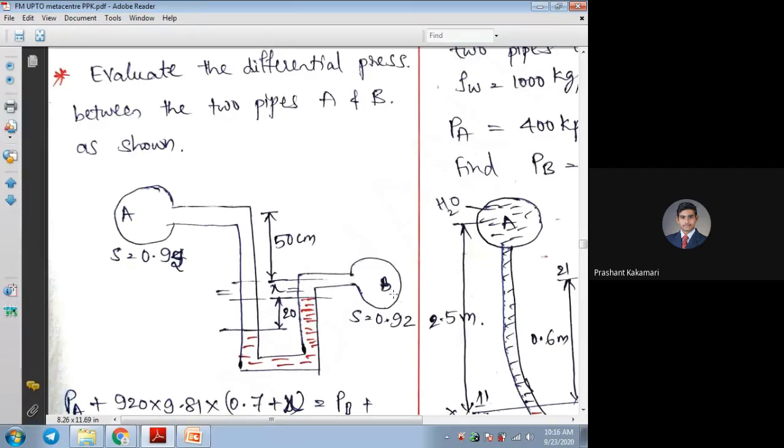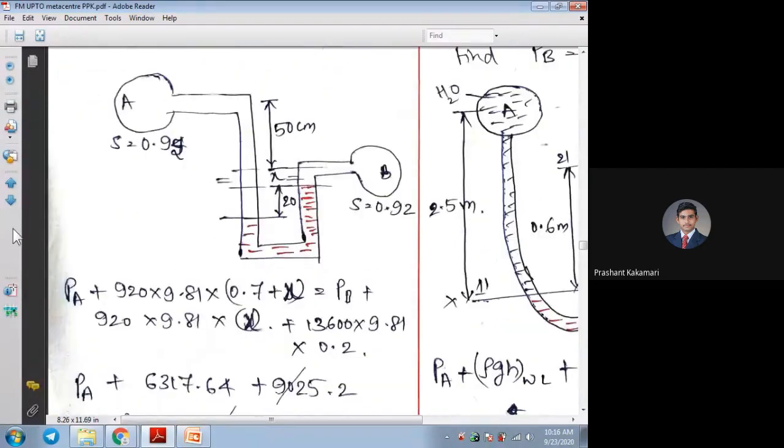Okay, so now coming to writing the equations. Again, I recall the whole procedure to write the equation. From the pipe, whatever pressure is coming on one side, we can take as positive. And whatever liquid levels are coming downside, we can consider as positive. The liquid levels which are rising upside on the other side, we can write on the other side of the equation, or you can subtract it, with the same pipe.